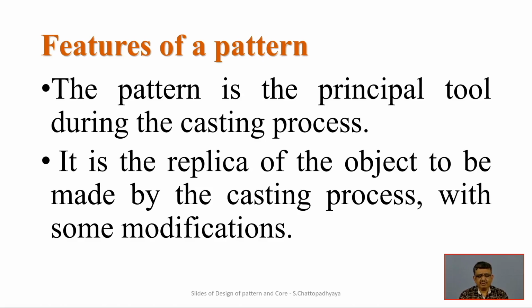Some modification has to be there, because in many cases the designers will specify the object, but will not specify what kind of pattern will be most suitable to make it. That kind of analysis of the designs in terms of manufacturing has to be carried out by the people related to patterns. In many of the big casting houses there is a pattern making shop where people are very experienced and expert in pattern making, and they utilize many woodworking tools to come out with a very good, effective and appropriate pattern.